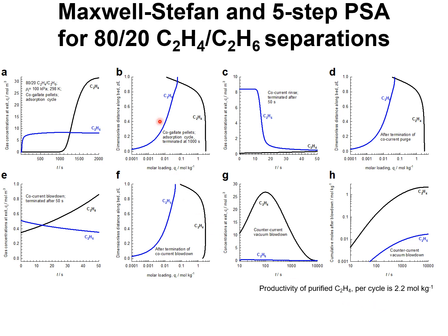So the takeaway message for my presentation is: use the LDF approximation at your own peril. For PSA modeling, it is important to properly account for thermodynamic coupling effects and adopt the Maxwell-Stefan formulation.